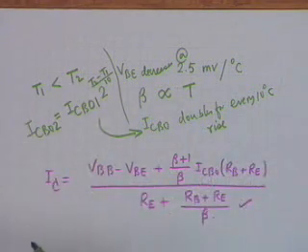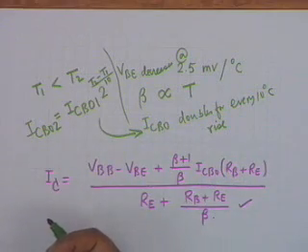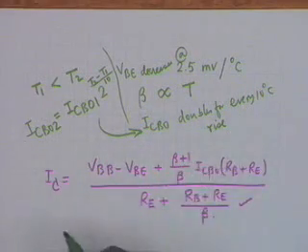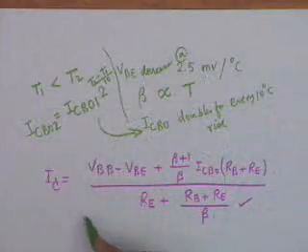It also can be affected, besides temperature, even if you keep it within a temperature stabilized enclosure, by a replacement of transistor. A transistor goes bad in an amplifier, so you pull it out and put in another transistor of the same type, but you know beta has a large spread. It can vary by as large a ratio as 1:6. If the original transistor was a beta 30, the new one may have a beta of 180. But even then, you do not want I sub C to change, you want I sub C to be stabilized, and therefore we must examine this expression as to how this stabilization occurs.